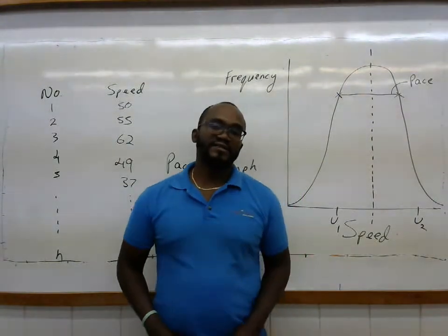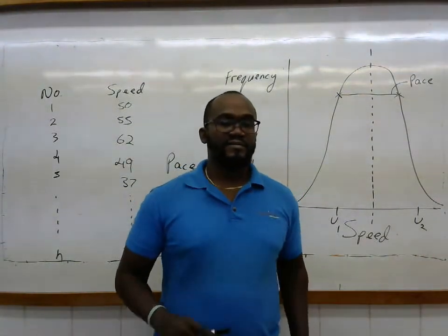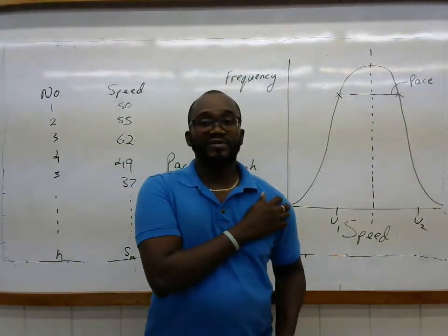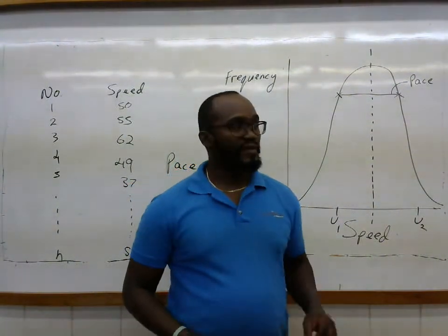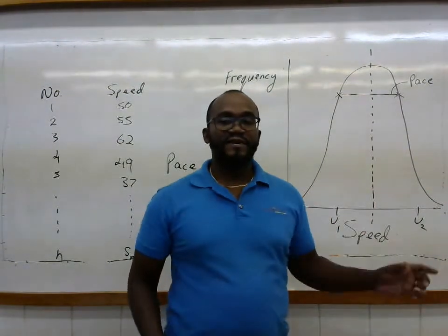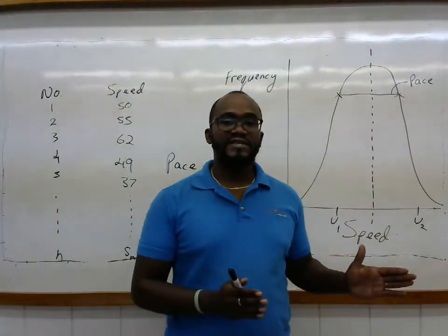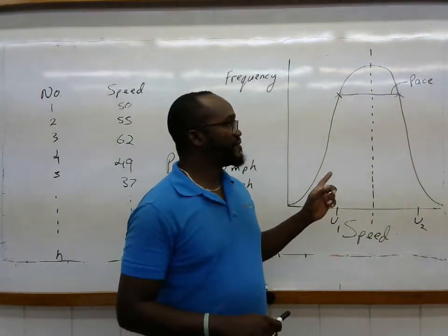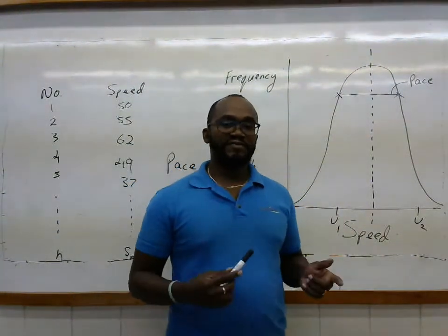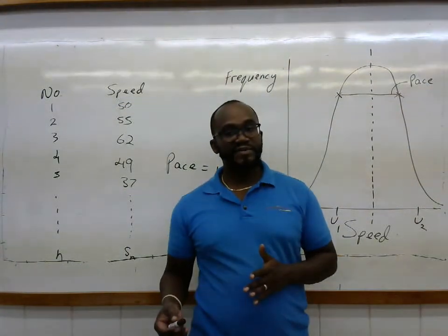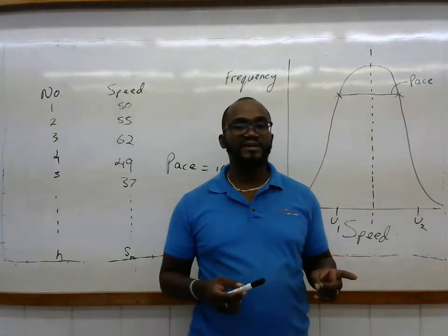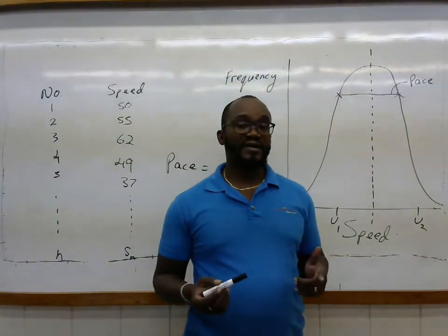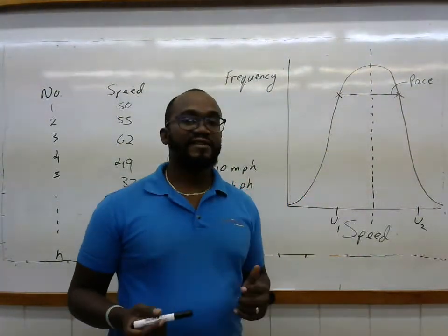There is research that suggests that, apart from the posted speed limit, it is actually safer if vehicles are mostly traveling at the same speed with little variation between them. In other words, the more the variation in speed, it is postulated, and in some cases it has been proven, the more likely there is to be an accident, and the less safe the roadway.